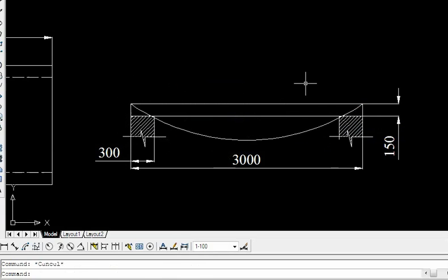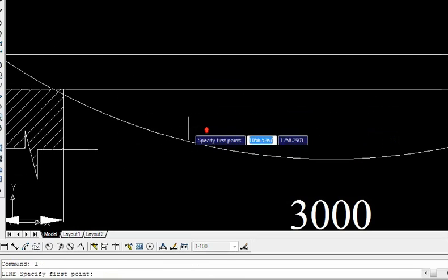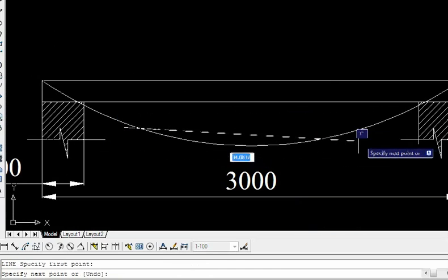I can show the sagging moments here. To avoid this bending downwards, we need to provide the steel in this form, like this, which I am showing in magenta color. You can see here.